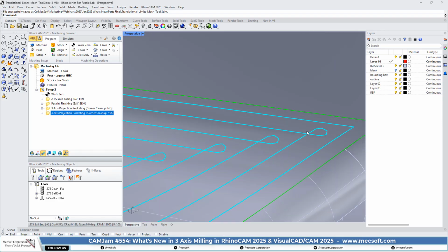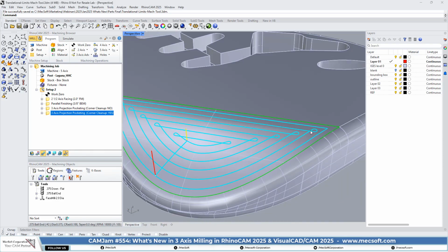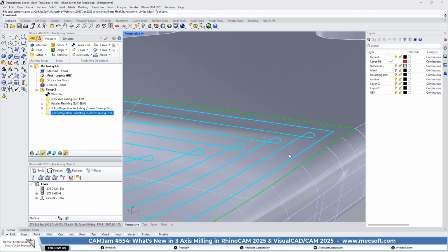In effect, it's creating a high-speed toolpath in 3-axis, where the tool, instead of just stopping and starting, can continue past, do this loop, and go around. Each of these angles is less than 90 degrees, so it's a lot easier on your router and also on the cutting tools, and you get a better surface finish.